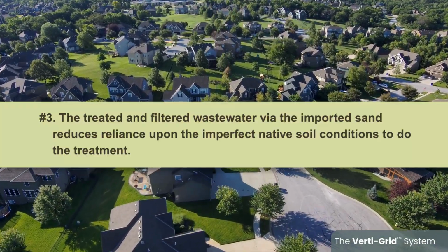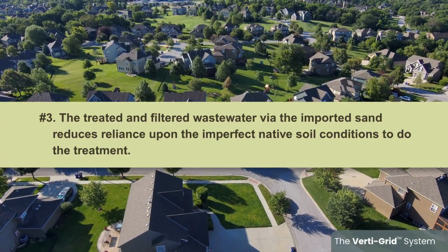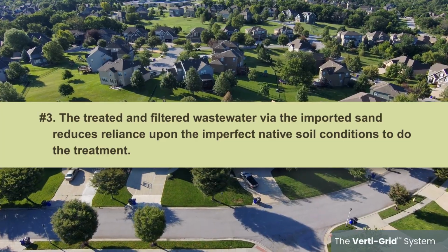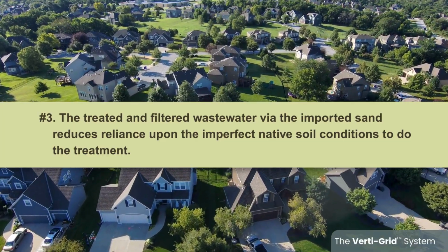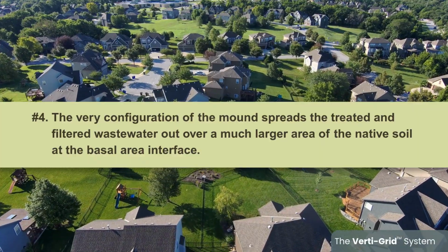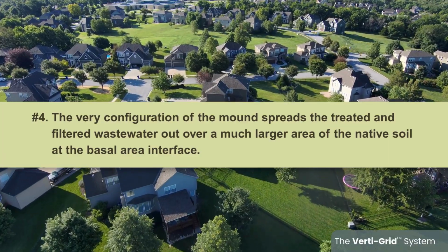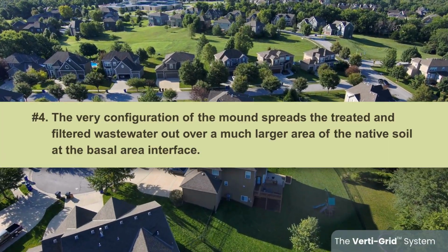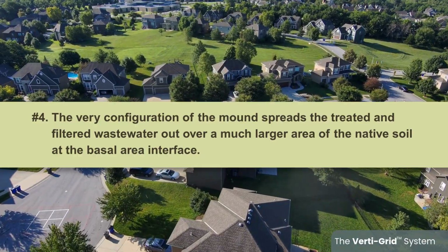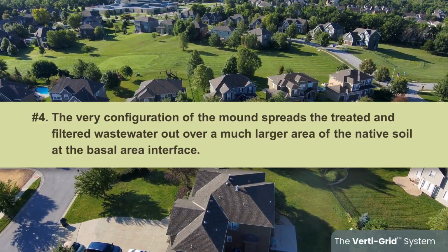The treated and filtered wastewater via the imported sand reduces reliance upon the imperfect native soil conditions to do the treatment. And 4. The very configuration of the mound spreads the treated and filtered wastewater out over a much larger area of the native soil at the basal area interface.